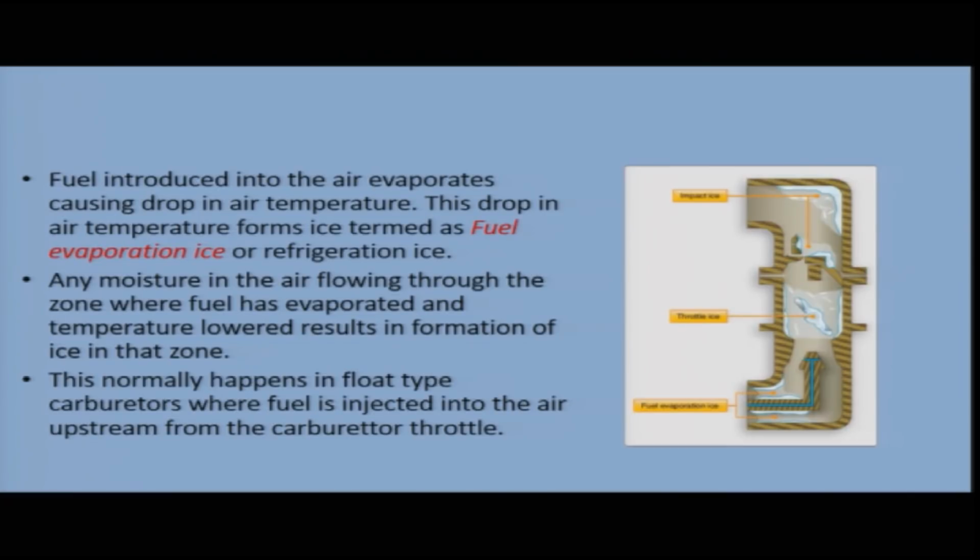This fuel evaporation ice is also called refrigeration ice. When the fuel is introduced into the air, it evaporates and causes a drop in air temperature. This drop in air temperature forms ice, which is termed fuel evaporation ice or refrigeration ice. When air flowing through this zone, where the temperature is lowered because of fuel evaporation, has moisture in it, ice formation will take place in that zone.